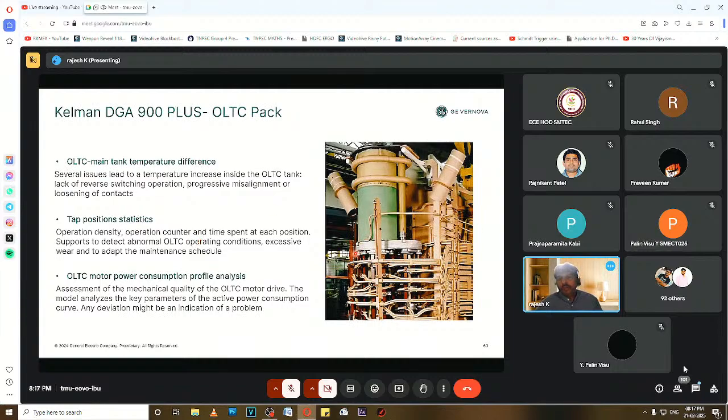Okay. This will be fully immersed in a tank. So this is a transformer inside. This is the picture. And you have the tap from the high voltage where the OLTC will move. It's an on-load tap changer. Since it moves during normal operation with the heavy load, the arcing will come. So you need DGA, particularly ethylene, acetylene, hydrogen, to monitor that.